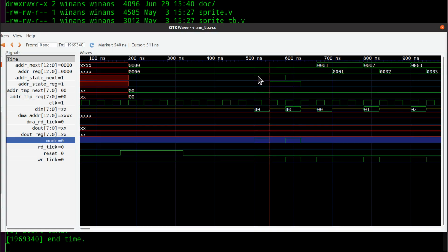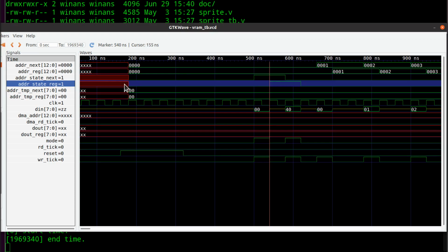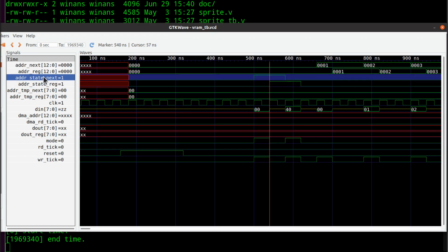That's why this propagates to the state register, which is updated on this leading edge here and not this one over there. Why did it go from 0 to 1 here? It went from 0 to 1 after the leading edge of this clock, from the combinational circuit that sees mode 1 go high. Therefore, if it stays high on the next leading edge over here, then the state machine is supposed to propagate this next signal here into the register over there. The real latch is the reg. This thing over here is the output of a combinational circuit.